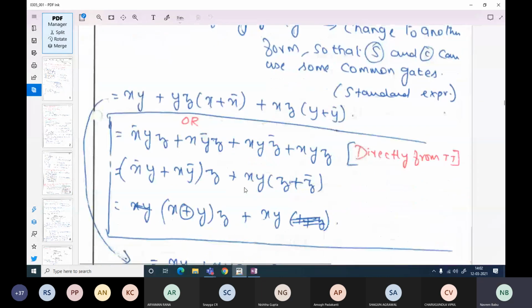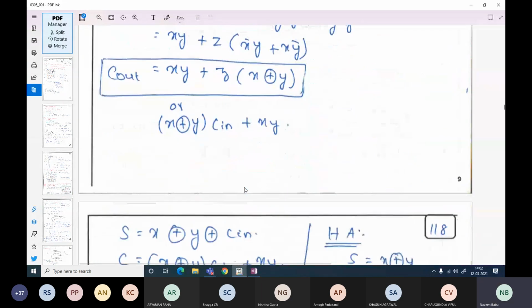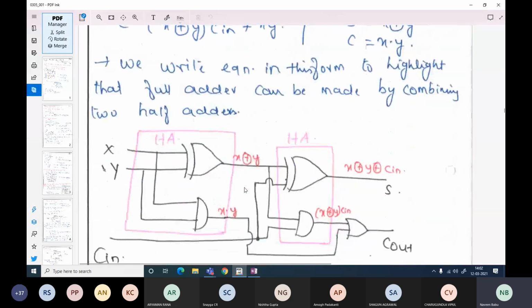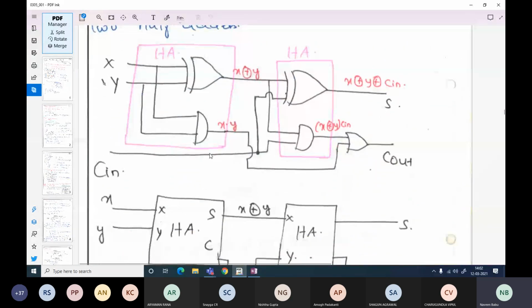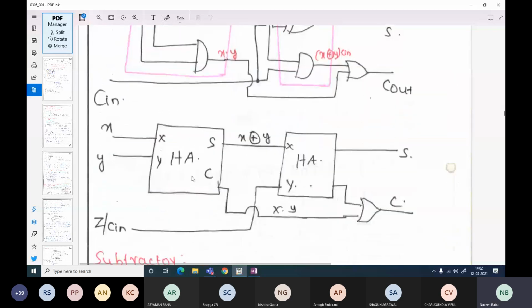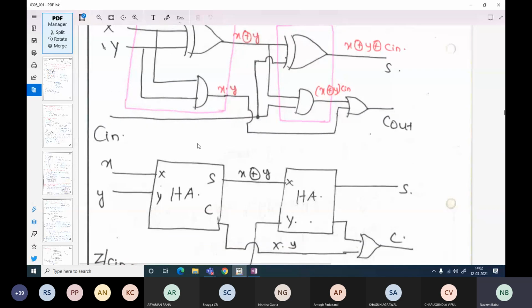Similarly, on those lines, your full adders can be implemented either using a gate level design, something like this, or since your gate level design of a full adder already contains a half adder circuit, you can design the full adder circuit with half adder blocks. The advantage here is that in the market you have ready-made ICs with multiple half adder blocks inside.